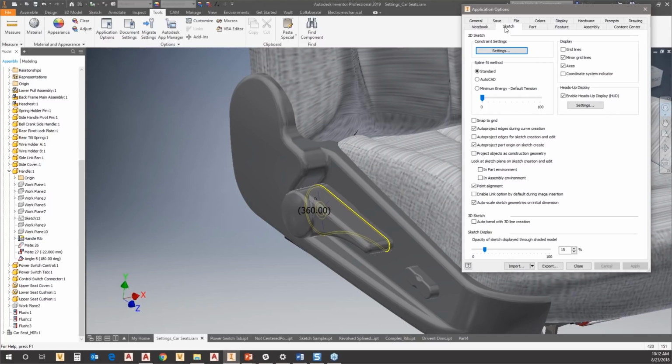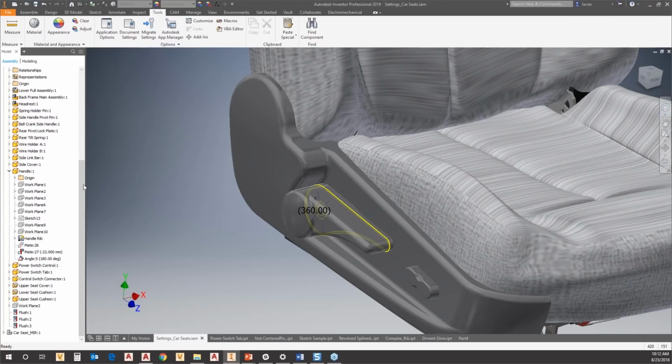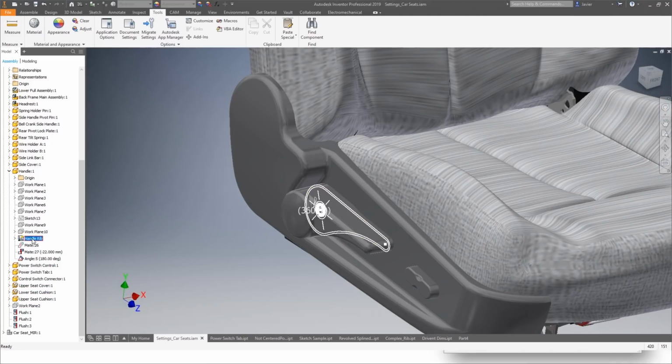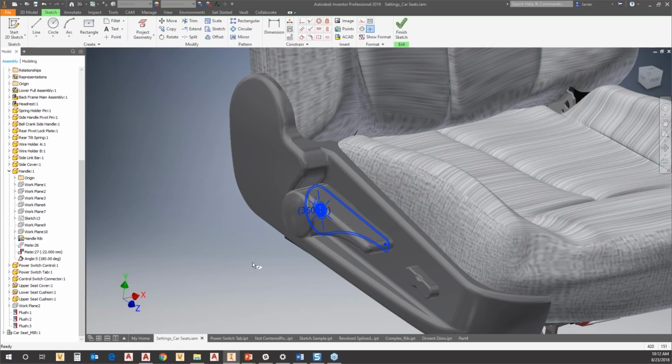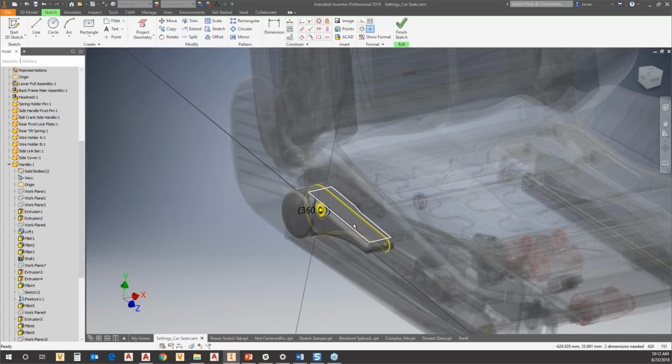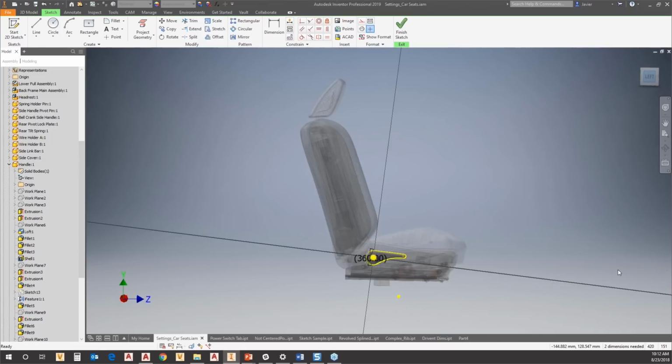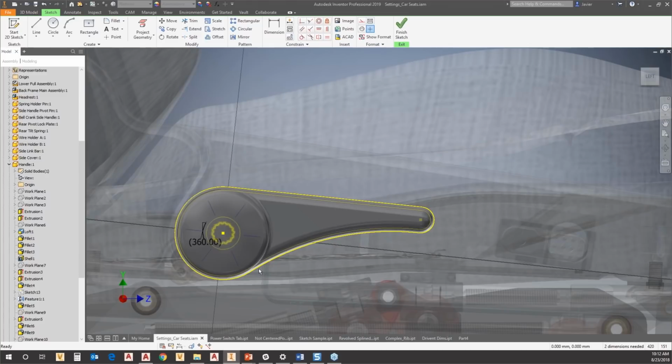And if I want to go ahead and edit it, since I have some of these other settings turned off, and I'll go back to the sketch tab here. There we go. In part environment, I don't want to look at this anymore. I could start editing that sketch right away. So if I double click, okay, it's not going to do a look at immediately. And so I could just start working with the sketch as is, as opposed to it rotating and zooming in and doing that. Sometimes you want that, sometimes you don't. The point is customize it to the way you want to work.